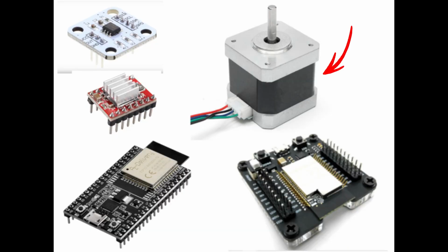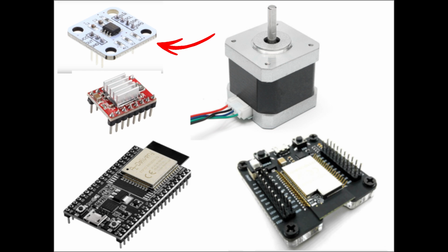To do this, we are using two NEMA 17 stepper motors, two AS5600 magnetic encoders, two A4988 drivers, and a cool dual microcontroller architecture. One controller is dedicated solely to reading encoder data for precise feedback, while the other acts as our mastermind, sending the exact pulse commands to the drivers.